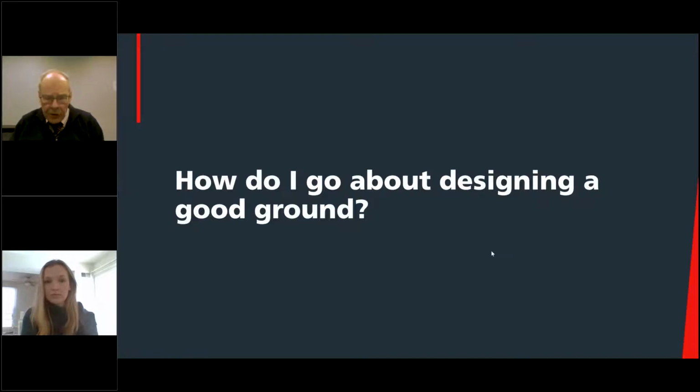The limitation of it is you can hit the law of diminishing returns, where, okay, the last time I added a rod, the resistance went down 10%. That's pretty good. When I add another rod, well, this time it only goes down 2%. So you can end up getting into a situation where you're driving and testing and you're getting smaller and smaller increments. And that can become counterproductive. It works a lot of times, but not always.